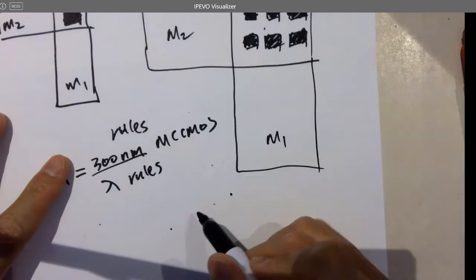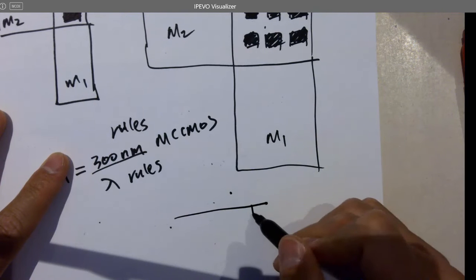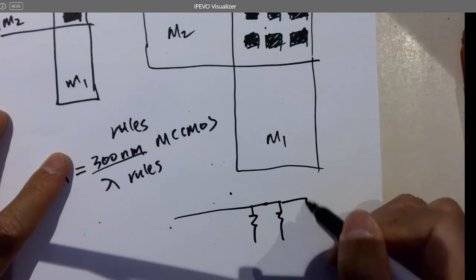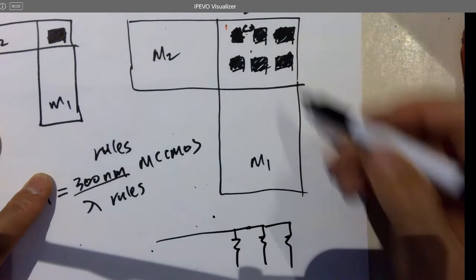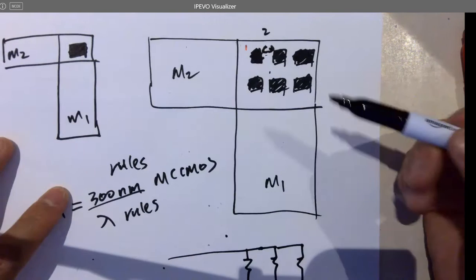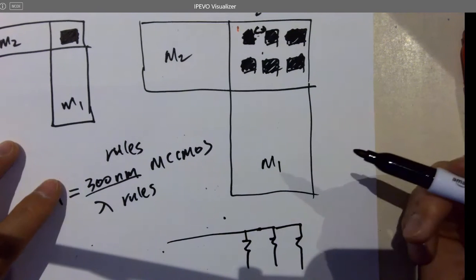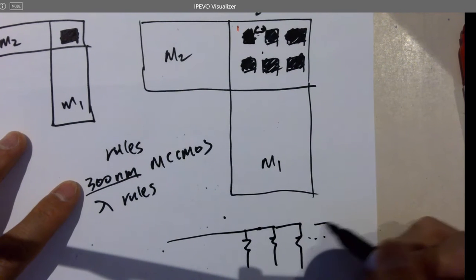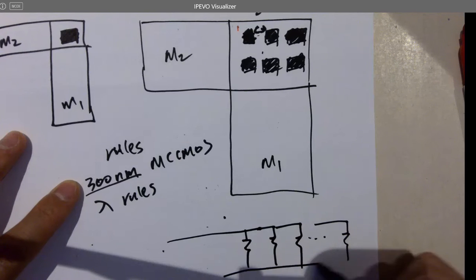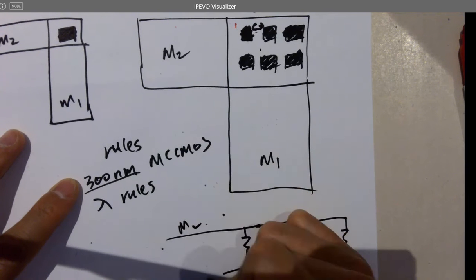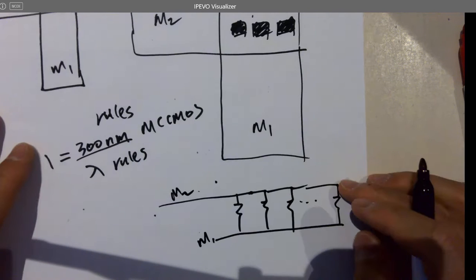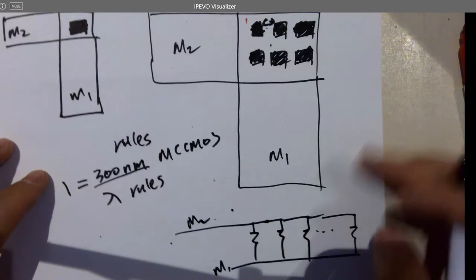Say you have a wire and resistors. There are 6 resistors, because a via is metal, and I can consider each one as a small resistor. So there are 6 resistors, and that's metal 2, that's metal 1, making contact between these two.